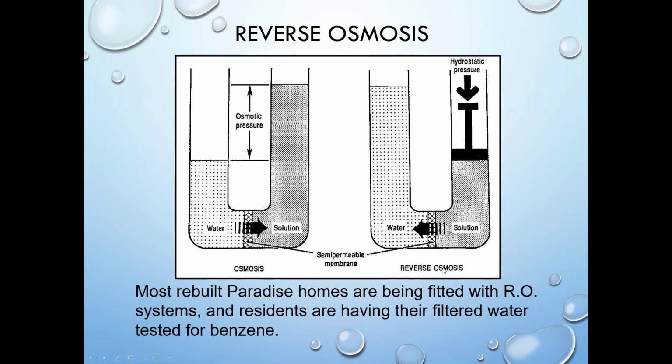One of the last disadvantages of reverse osmosis involves this semi-permeable membrane right here, okay? When you're first starting to use your RO system, you have to chemically treat your membrane with some chemicals that will basically extend the life of the membrane. And even then, eventually these membranes may rupture, okay? Kind of like a filter may rupture as well. And so these membranes have to be replaced, and that's another expense that gets passed on to the consumer, of course. So this isn't just a system that you can use over and over and over again. It has some parts that need replacing every so often.